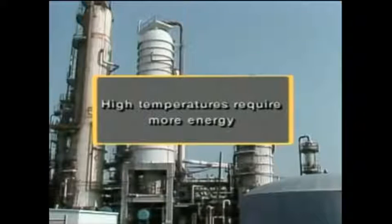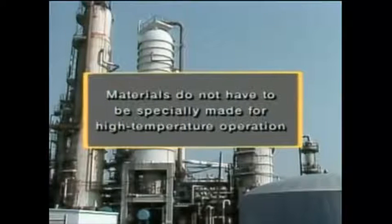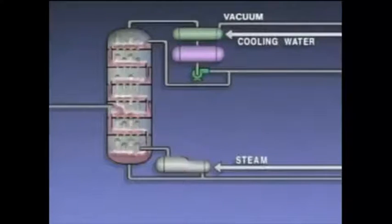Structurally, there are two basic differences between a vacuum tower and a tower that operates at atmospheric pressure. We can use this illustration of a vacuum tower system to see what the differences are. For example, a vacuum tower is usually larger in diameter than an atmospheric tower, and the trays are farther apart. These differences are necessary because a vacuum tower generally produces a larger volume of vapors than an atmospheric tower. Another difference is that a vacuum tower has an additional system that creates and maintains a partial vacuum in the tower. The partial vacuum is maintained by either steam jet ejectors or a vacuum pump. These components draw gases out of the tower through the condenser.